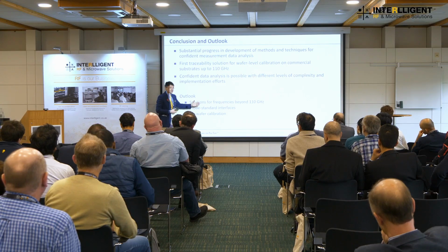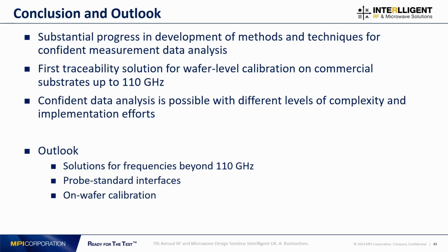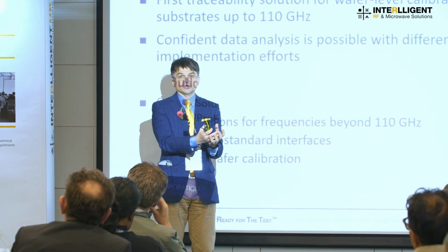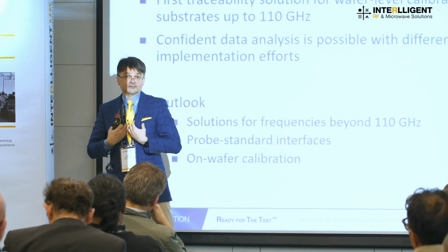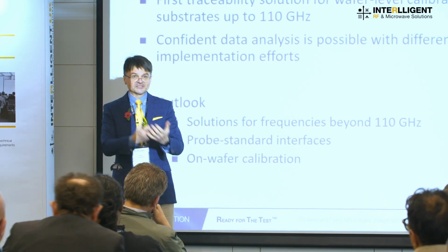And this is the outlook for the next couple of years of work, and engineers are working on it. First of all, extending this solution up to much higher frequencies than 110 gigahertz. Then understanding the contributing factor from the probe-to-standard interface and how to disconnect these two from each other. And also switching it to on-wafer measurements, actually in your customer environment, because traceability is nice if it's established on a commercial calibration substrate. And believe me, as a vendor of calibration substrates, I would love to sell you, for a lot of money, a calibration substrate with an established traceability chain.